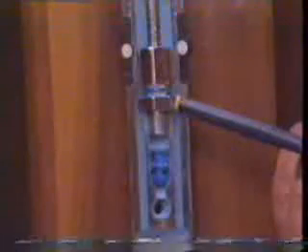At the same time, casing pressure comes through this metal port and moves upward across the check and under the seat, providing an upward force trying to push the ball off the seat. Together, the casing pressure and the tubing pressure will overcome the spring calibration pressure. It's obvious that the tubing pressure flowing through these bypass ports acting on the bellows is the predominant opening force